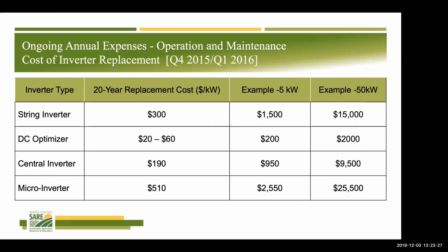Also cleaning the filters and just making sure that, through mowings and dust and whether there will be animals in the area, the filters are clean so the inverters are breathing properly and not becoming overheated or heat stressed.